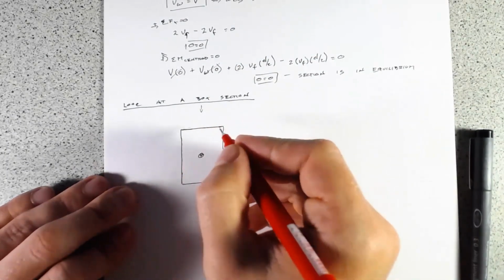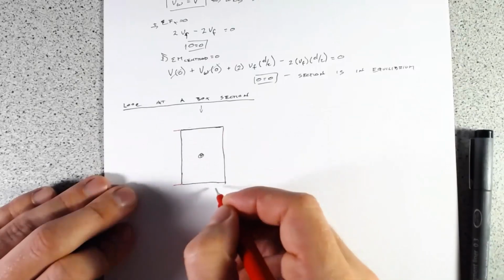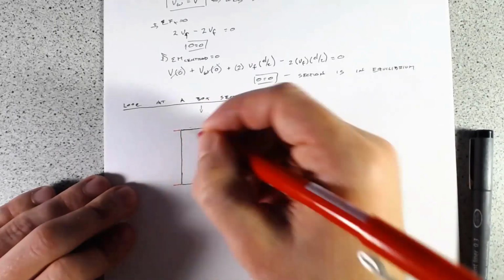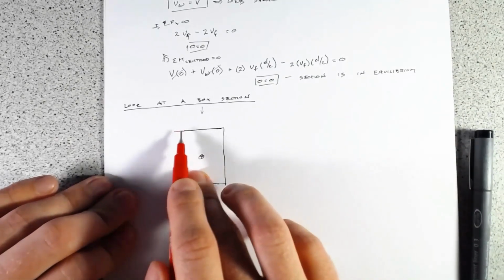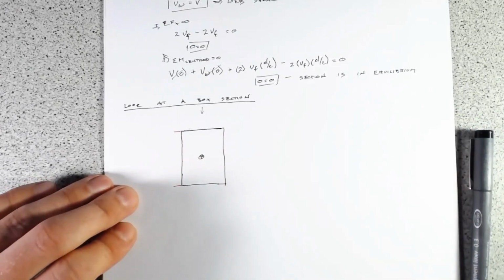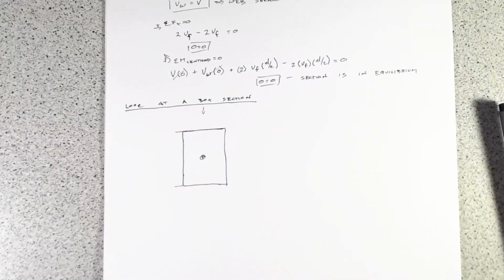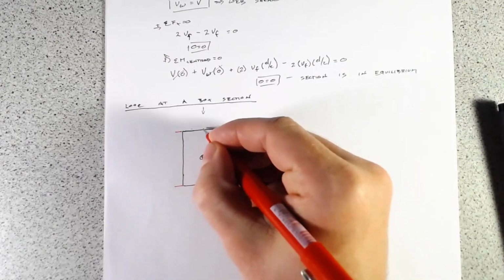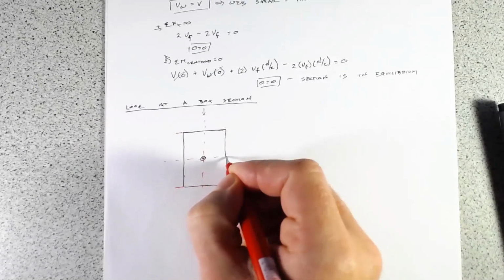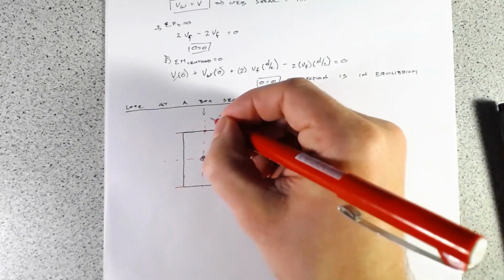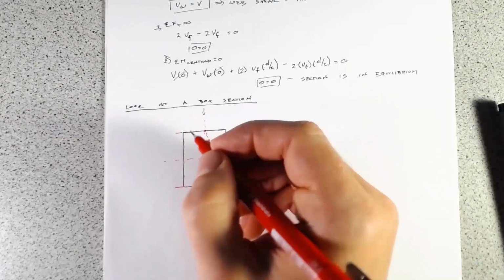So we know that our vertical pieces have to have a parabolic distribution. And we know that the middle one has to have a horizontal one. And we know that we have to have equilibrium at a corner, for those equal and opposite forces to be able to flow through there. And so what we find is that right at the center, Q equals 0. And it's really based on symmetry.